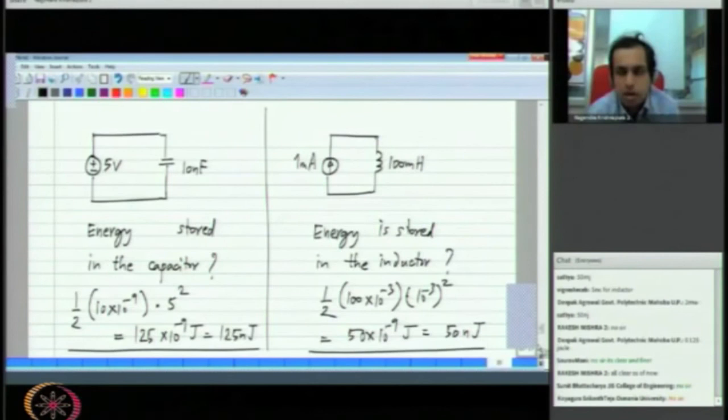So what we have learned in this section is the definition of power and energy in electrical elements. An inductor and capacitor store positive energy, and it can also be recovered. They don't really dissipate or lose any energy. So that's an important feature that distinguishes them from resistors, which constantly lose energy. They continuously dissipate power as long as some current is flowing through them. And the voltage source and current source are the sources of energy, but it is possible for them to also dissipate energy or power.